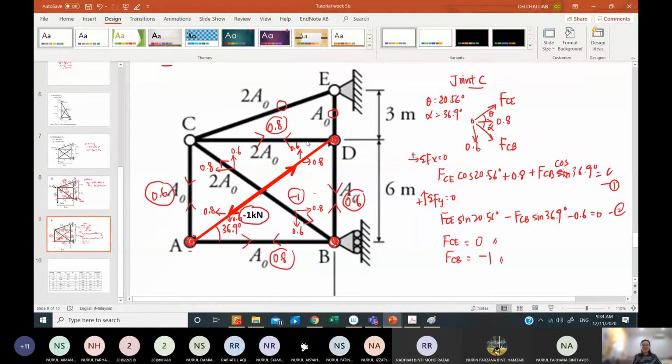Then you can prove that in these systems, this is all 0. If you already know that this is all 0 because there is no applied load for your BX, EX, and EY, actually you can skip this step and directly solve for the members EC, ED, and so on. So now you have already solved for the nodes.